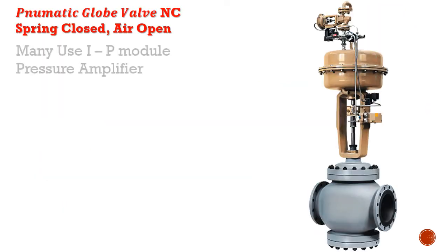So a lot of these valves use a current to pressure module. And then that pressure module uses a pressure amplifier. And again, larger valves require much more air pressure. So there's a set of standards, and then there's some independent ones based on the actual application.